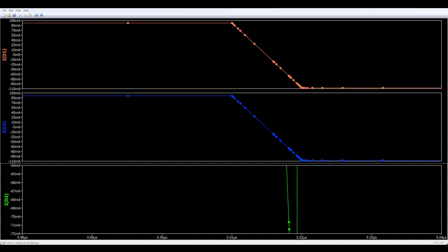Now, keep in mind, switching diode, it's meant for signals and logic, whereas fast recovery and regular diode can obviously handle a lot more, but it's especially made for very low voltage signals. And it can only handle much lower current, I think maybe in the hundreds of milliamps. It really depends on the model, but the switching time is like a couple of nanoseconds as opposed to a couple of hundred nanoseconds for a fast recovery or microseconds for a rectifier.